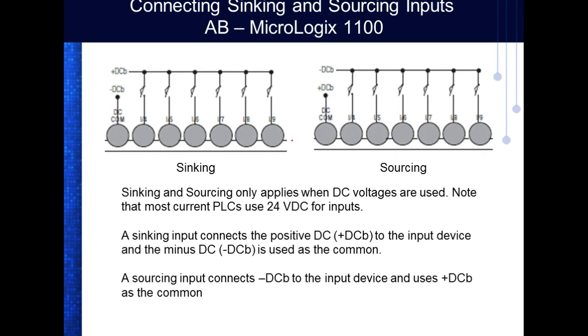On a lot of these fixed PLCs, now when you have a DC rack PLC, normally you buy either a sinking module or a sourcing module, and they are not interchangeable because they power up down the rack. Since they power up down the rack, you can't jumper which power supply comes into those modules. So with these modular PLCs, you specify what type of module you want. If you look at the 504s, I think the input module is a sinking module and the output module is a sourcing module. And it's written on the module itself.